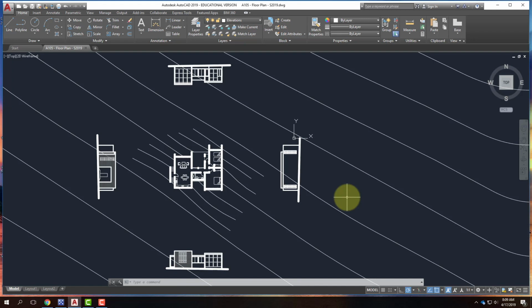When we switch to Paperspace, that's where we apply it to a sheet of paper. That's why it's called Paperspace. We put our drawing on that sheet of paper, and we scale our drawing appropriately for that sheet. If you were working in a firm doing working drawings using AutoCAD, obviously not Revit, we're speaking just to AutoCAD right now, you would be using Paperspace quite a lot. There's a whole series of steps for how you create your drawings and how you have what's called a sheet set, with a bunch of these Paperspace layouts so that you can create a whole big working drawing set.